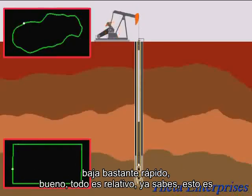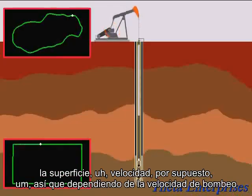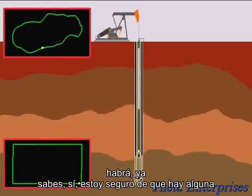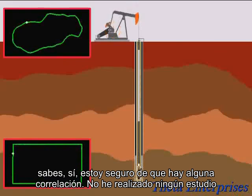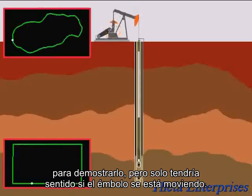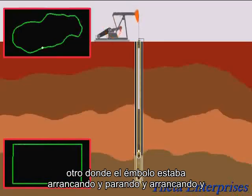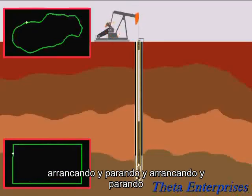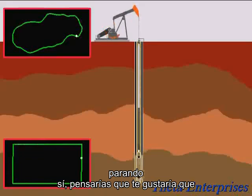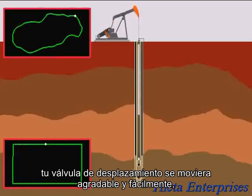Well, it's all relative. This is relative to the surface speed, of course. So depending on the pumping speed, I'm sure there's some correlation. I haven't done any studies myself to show that, but it would only make sense that if the plunger is moving faster, there'll be more wear. Or maybe the other one where that plunger was starting and stopping and starting and stopping. Yeah. You would think you'd like to have your traveling valve moving nice and easy, not a lot of starts and stops.